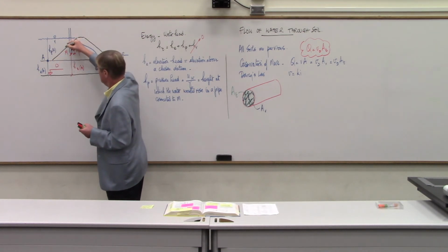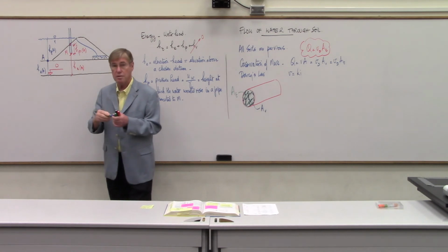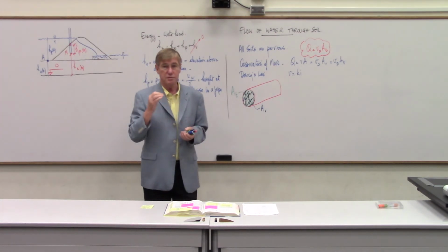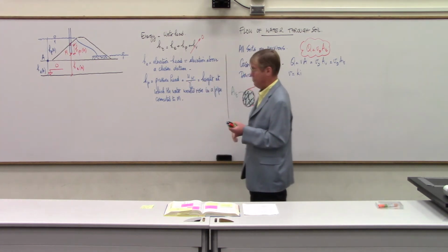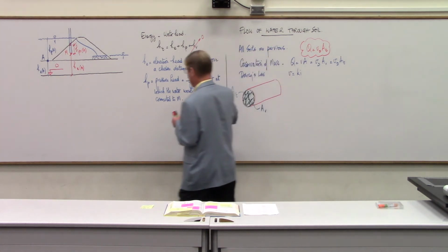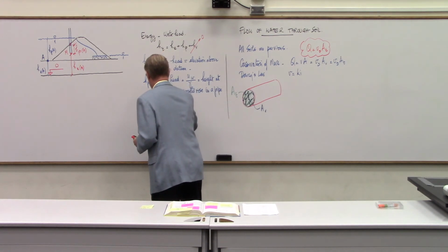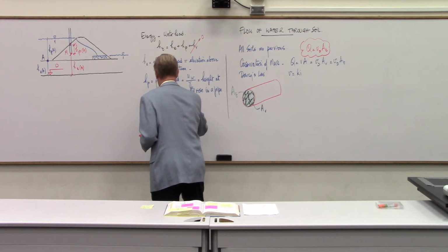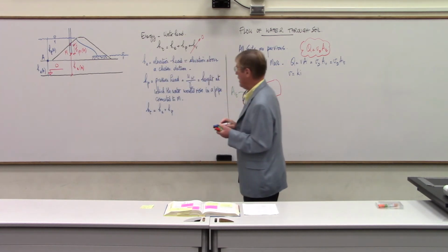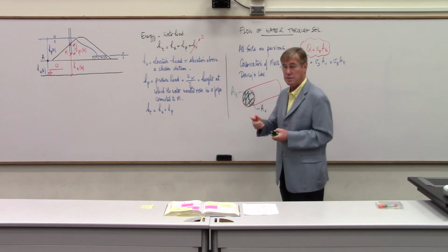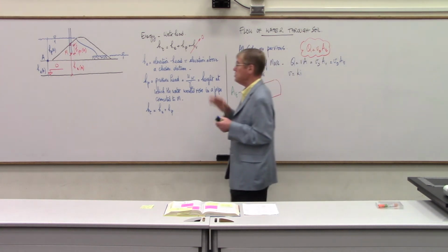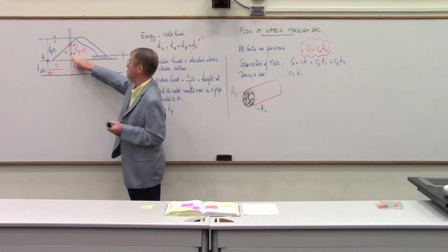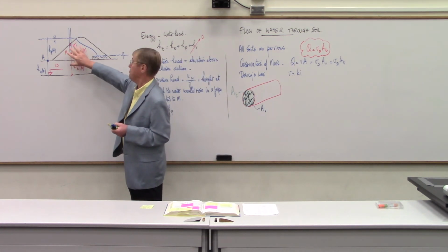But here the water is moving. So you cannot make that same assumption. You have to find a way to determine that pressure head in another fashion. And then the total head is simply the elevation head plus the pressure head. Okay? In the problems that we're going to go through, because we need to solve the seepage problem, we need to be able to find what this H_P is everywhere in the dam.